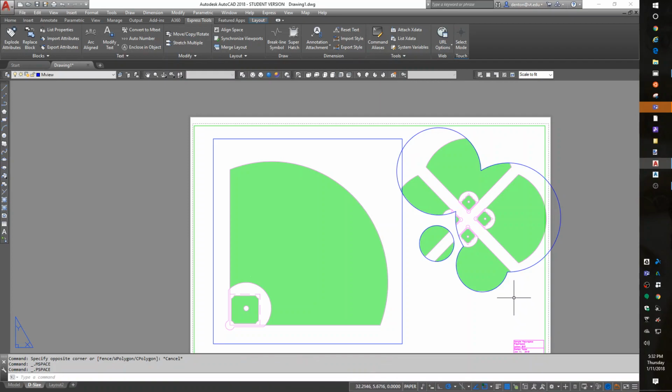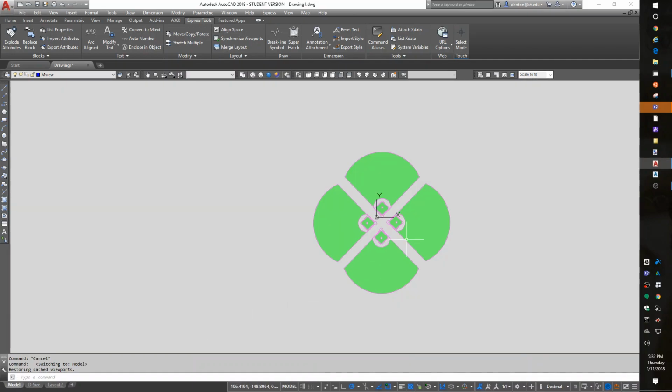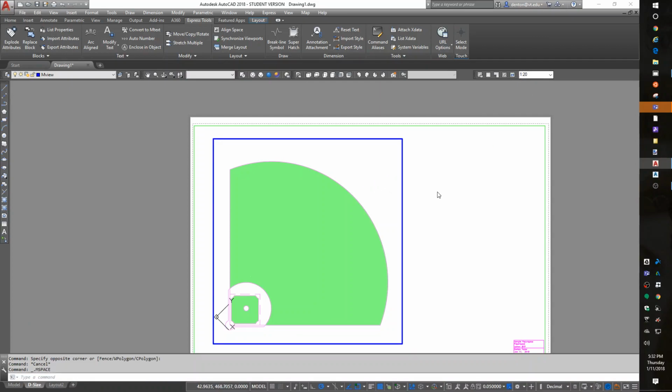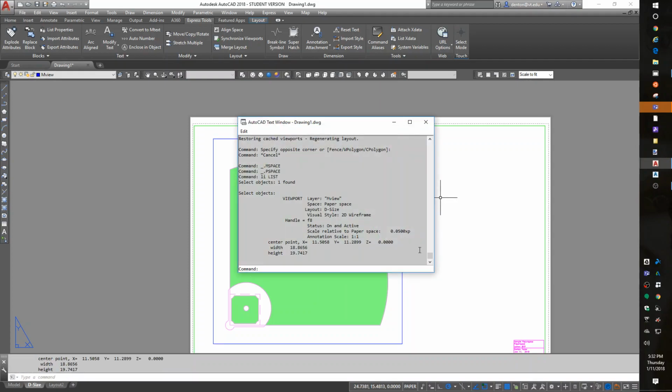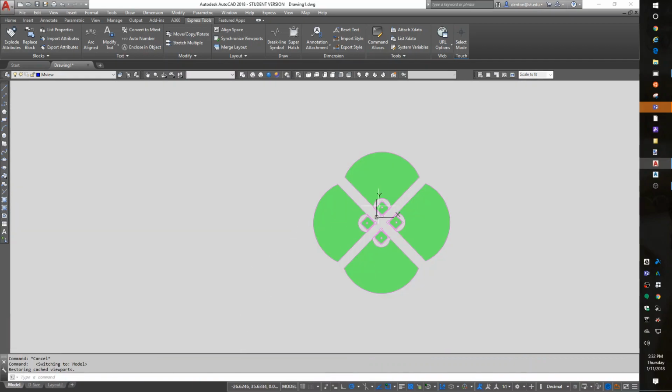Okay. Paperspace, erase the object. One other thing I want to talk about is if I go back to the Model tab, what did I make this scale? 20 or 30? I don't remember. Double click inside, 20. Okay, so I made it 20 scale. I can also list my MView object, and it'll tell me what scale factor it's at, which is 1/20th XP. Okay, so I know 20 scale is the scale I intend to print this.